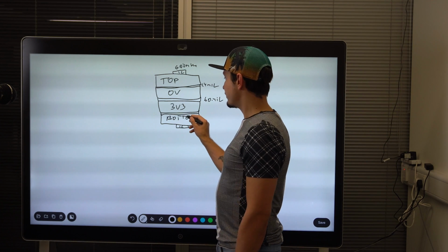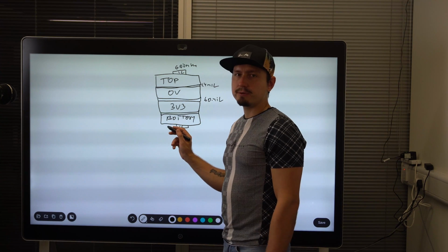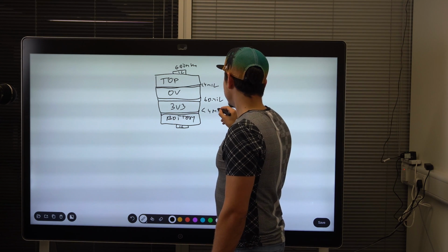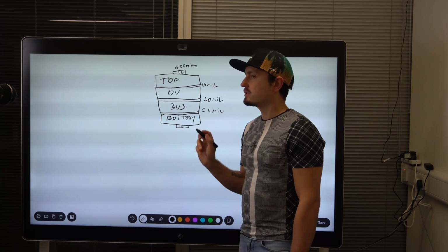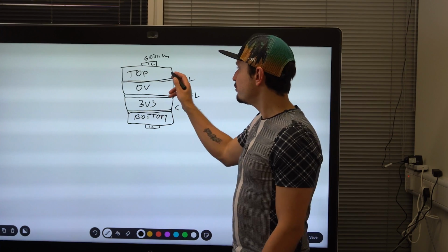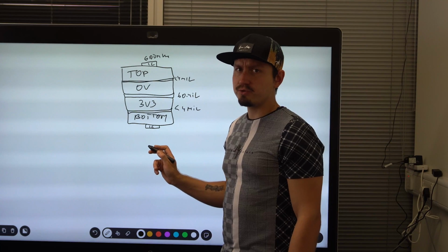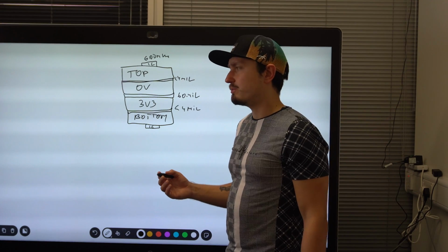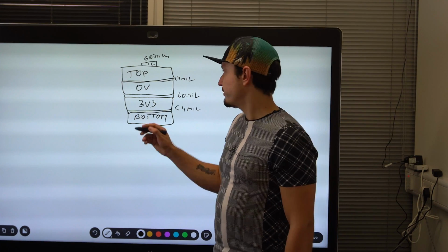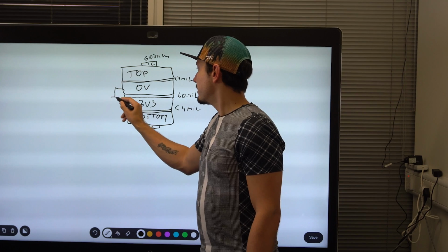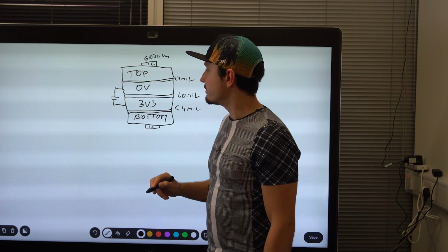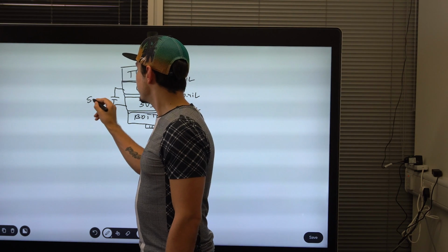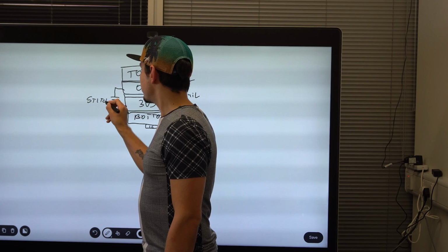where we may have another IC, maybe some DAC or anything. So this is obviously where we're gonna route some high frequency signals as well, so I will have the separation distance 4 mil or less. Again, very important, when we do change layers from top to bottom during routing, even though we want to avoid it, it is kinda necessary most of the time. I like to put in a capacitor at every point when this happens, which is called an EMI stitching capacitor. So I'm just gonna write stitch.